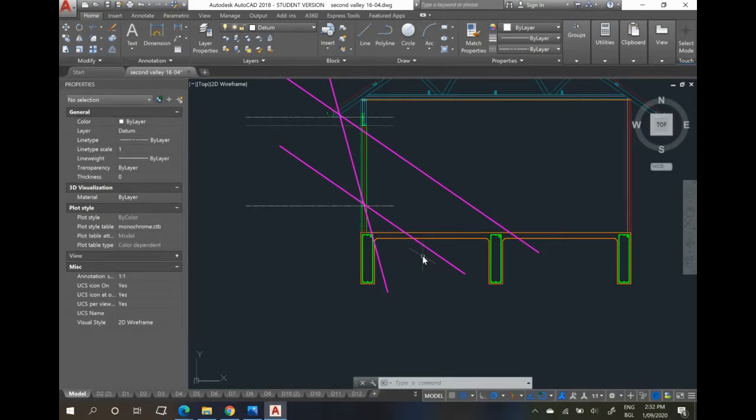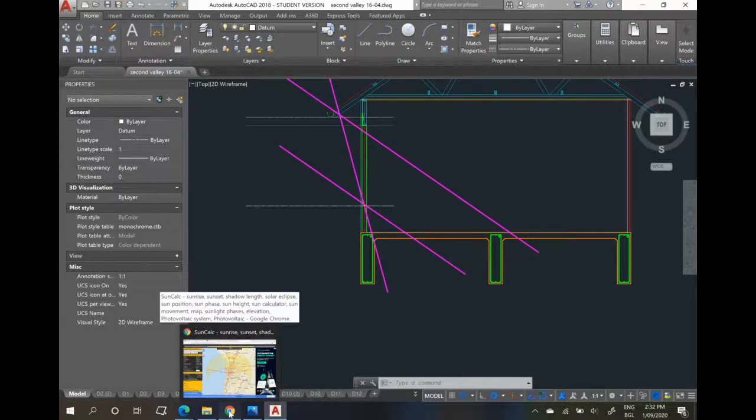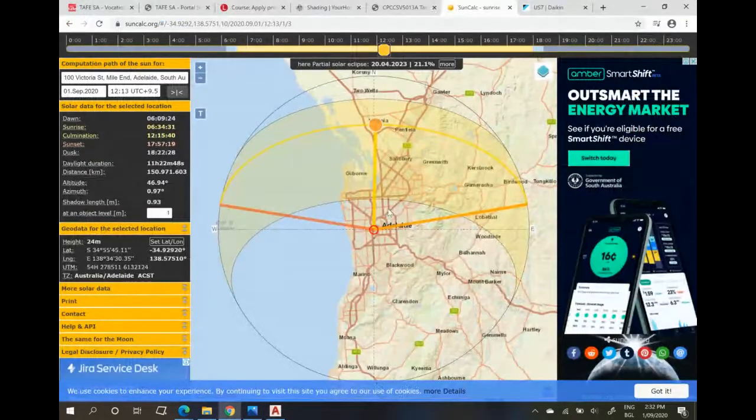Now it gets a little bit trickier when we go thinking about azimuth as well, because then our sun, once we tip our houses away from that due north, then the sun is coming in at a slightly different angle, and obviously when the sun is at a lower height during the day, it once again starts penetrating in through the windows in summer solstice.